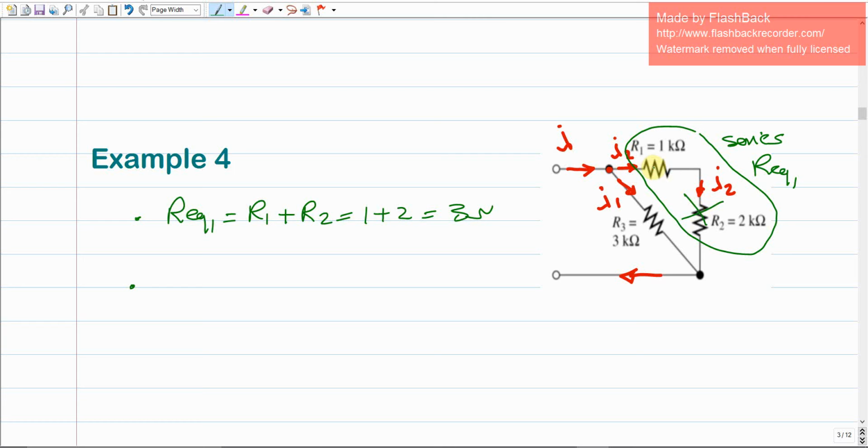So again, if we combine these two together, it looks like we get rid of one of these two resistances with an equivalent one. We are using just one of them, but with a different value, right? So we're going to end up with just one resistor, which should be in parallel to R3. Why should it be in parallel? Because the current has been divided over them.